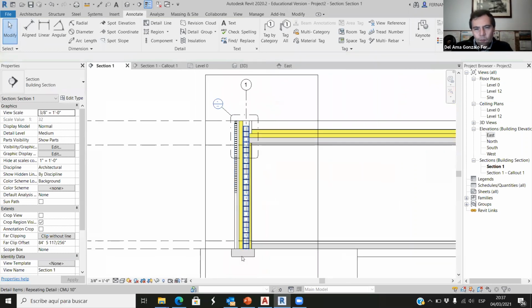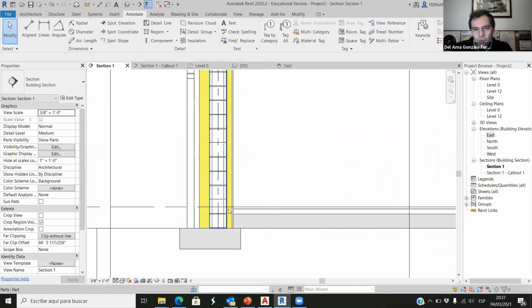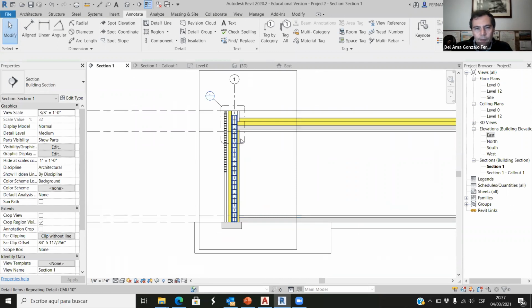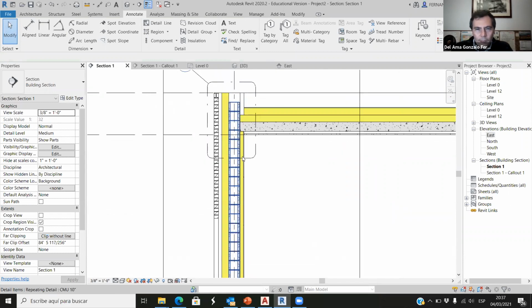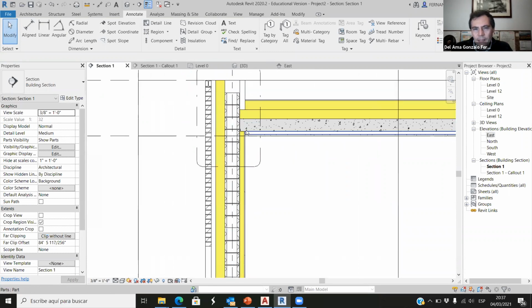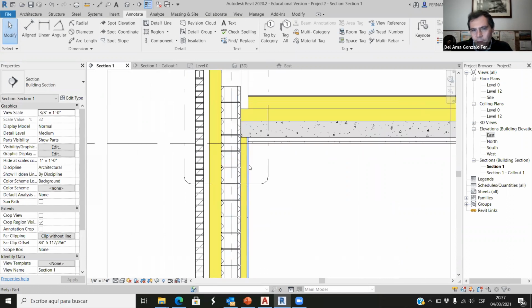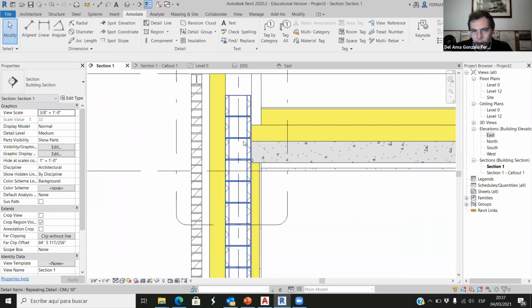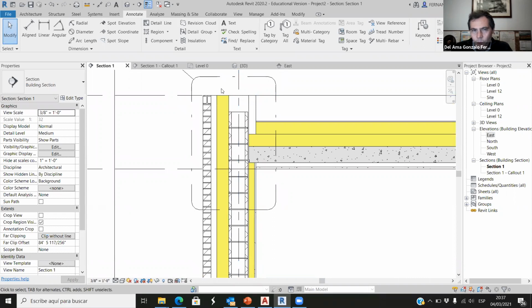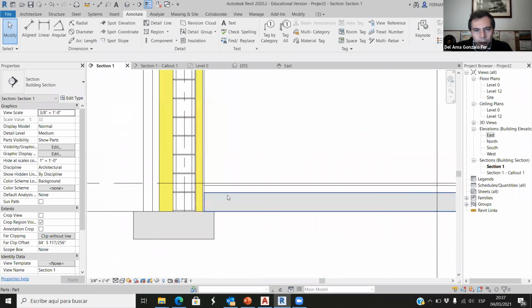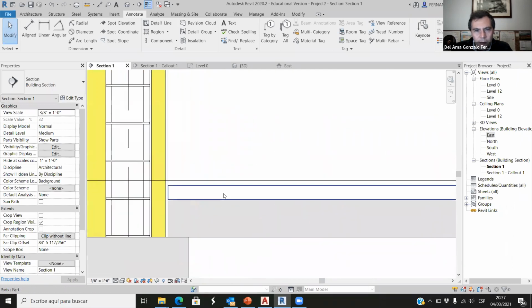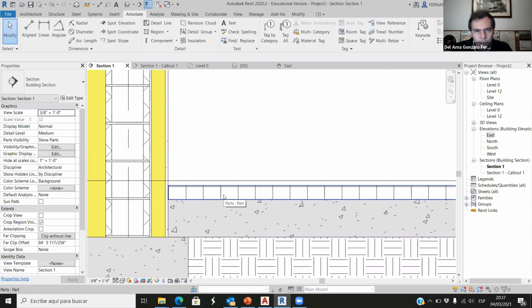And why do we do this? Okay, because we want to wrap our building. If we didn't have this as a thermal insulation, there would be a thermal breach here, and we don't want that. So you may say, okay, there's a thermal breach here because we will place some thermal insulation here on this cap again. And we need thermal insulation because this is the thermal insulating layer here.